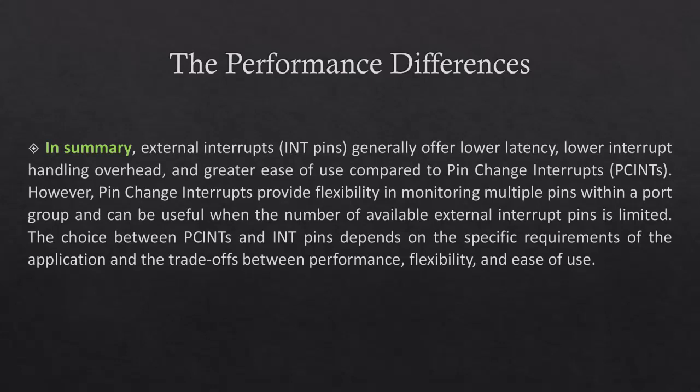The choice between PCINTs and INT pins depends on the specific requirements of the application and the trade-offs between performance, flexibility, and ease of use. My recommendation to you is to utilize microcontroller pins that have hardware interrupt capability as much as possible, especially when you require very precise timing for external interrupts.